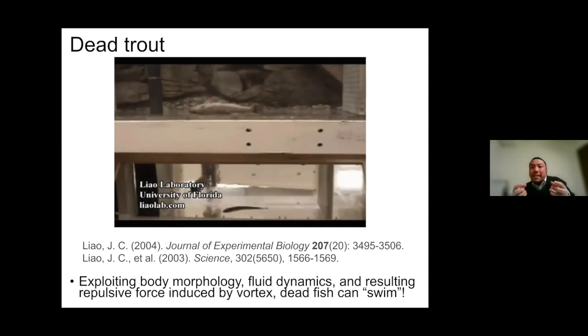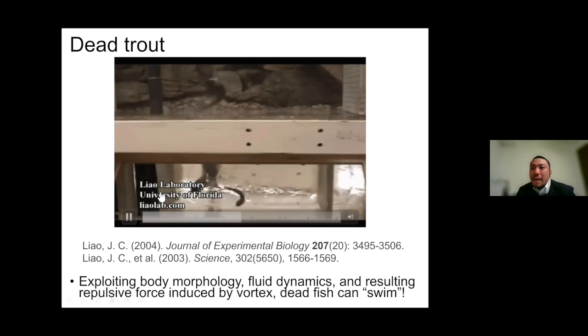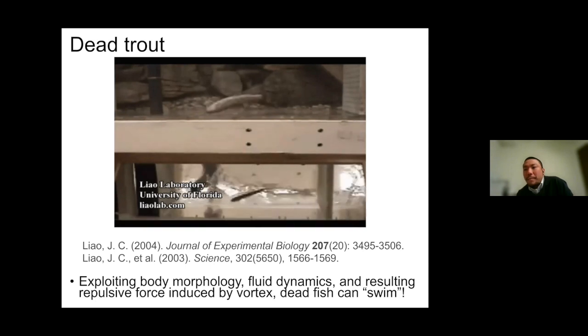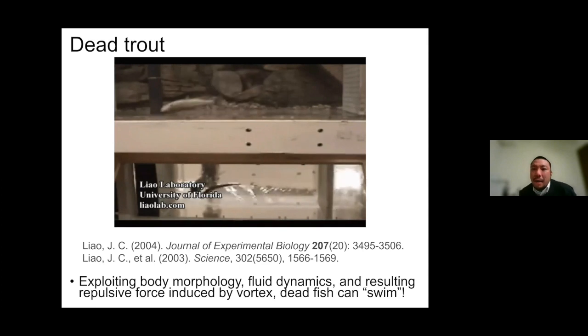And by using this natural material property and form of the fish morphology, and also actually it has a cylinder here, when you generate flow, it generates some specific vortex in the water medium. So using this complex dynamics in the water, and also the interaction with this material property, it can generate this kind of natural swimming motion.